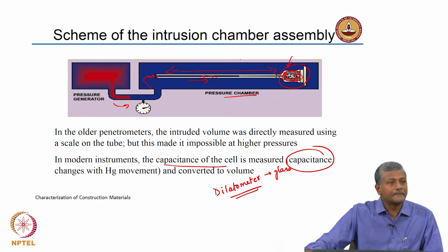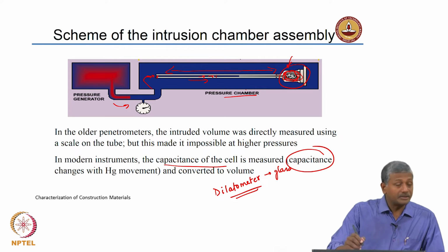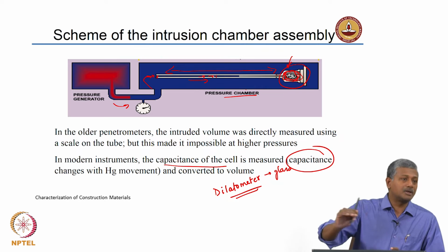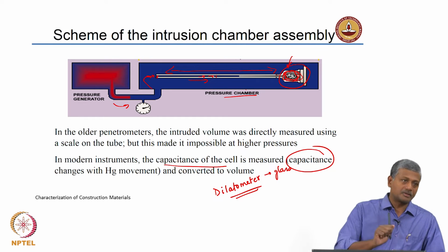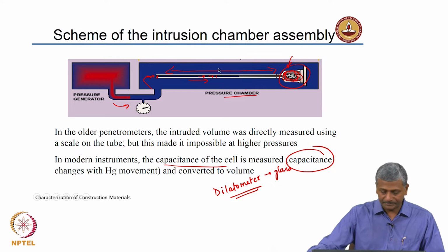The chamber is not... No, vacuum. The chamber is vacuumized, and then you are filling it in, you are flooding with mercury under vacuum, and then you apply the pressure which penetrates the sample pores.